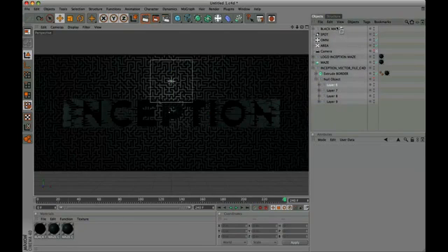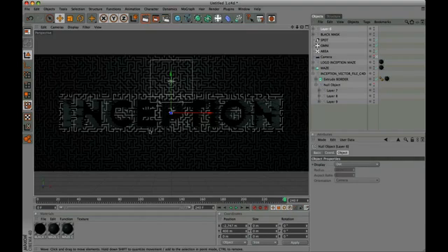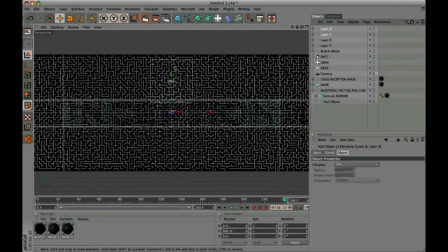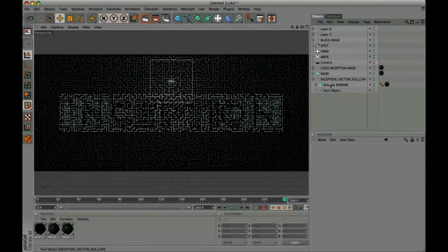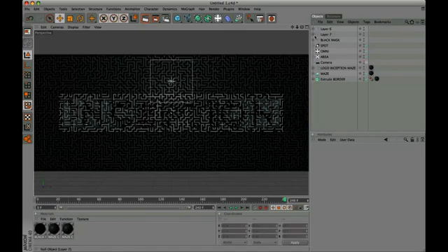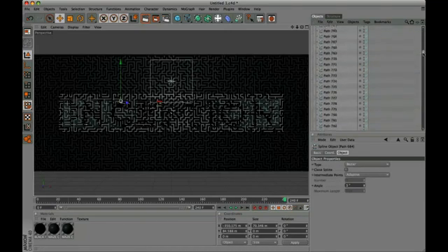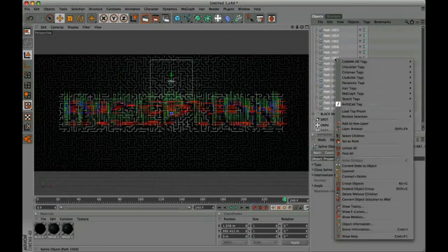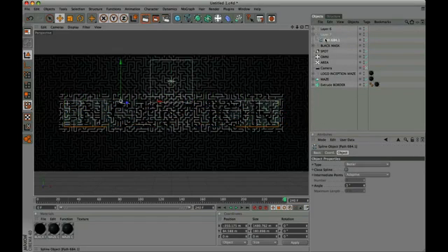Select the 6th layer and drag it all the way out. We repeat the same step with the 7th layer. These two layers contain the splines, which will be used for the positioning of the buildings. Select layers 8 and 9, and delete them. Drag Extrude Border outside the object, and delete the object imported from Adobe Illustrator. Connect the layer 7 spline, drag it out and delete them. Rename it Path Buildings inside.